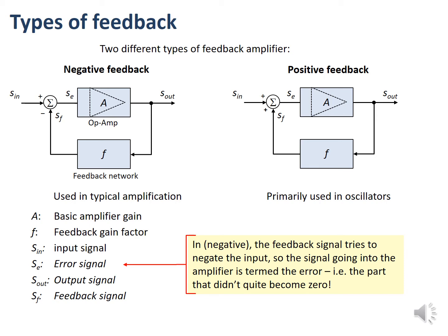But what we're more concerned with in this course is negative feedback. The signal is fed back through the feedback network and it acts in a negative way to subtract away from the incoming signal, and that's fed round. This creates a more stable situation and it enables us with the op-amp to control the amplification through the resistor networks that we're going to put around the op-amp. So we're going to concentrate on this negative feedback concept.